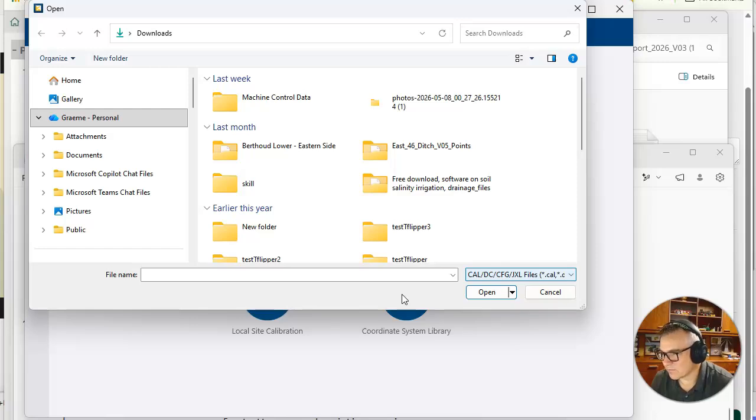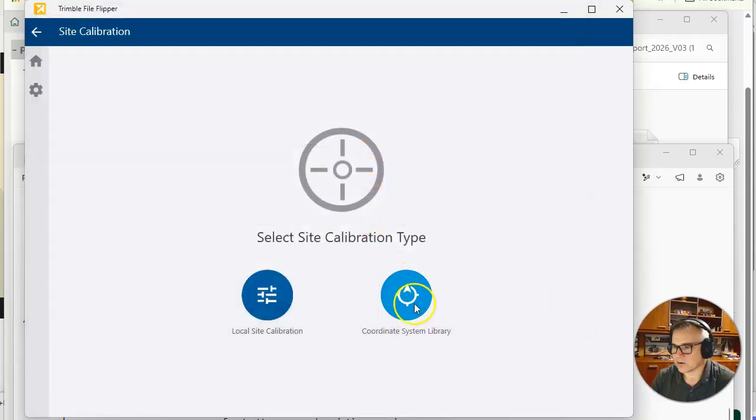It'll use those points to produce a calibration, because it has to basically convert a GPS latitude and longitude into your local eastings and northings that your design is in, and so it needs a way to do that calculation. This calibration file is effectively telling the machine control system how to do that latitude and longitude to easting, northing, and elevation conversion. But that's a lot more complicated. If you've got it using a standard coordinate system, it's straightforward.